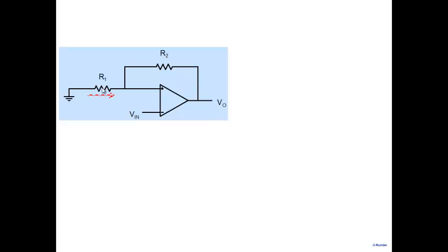So let me start here. The current here, how do I write the current? 0 minus the voltage now at the positive terminal, V plus, by R1. Okay. The op-amp's input impedance is still very high. It's not drawing any current. So the next thing, I write this current. This current should also be equal to I1. So I2 equal to I1: V plus minus V0 by R2. Right? Same. The only thing I've made is the assumption that no current is going into the op-amp, which is fine.